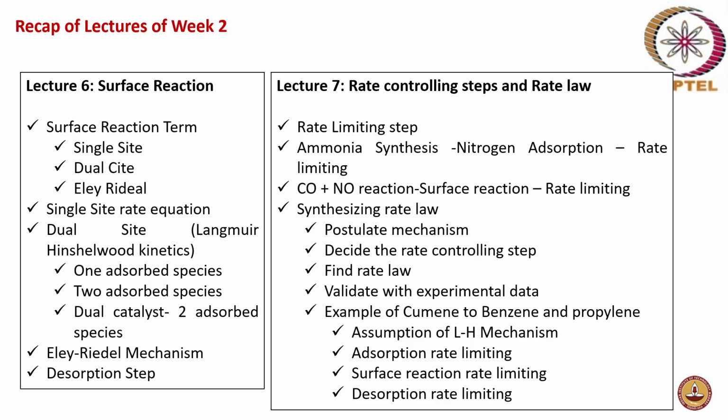What happens when there is a single site or dual site mechanism, and then Eley-Rideal mechanism, and then single site rate equation, and dual site mechanisms, especially the Langmuir-Hinshelwood kinetics, where there is one adsorbed species or two adsorbed species, or dual catalyst two adsorbed species was discussed, and then Eley-Rideal mechanism was discussed, and a desorption step.